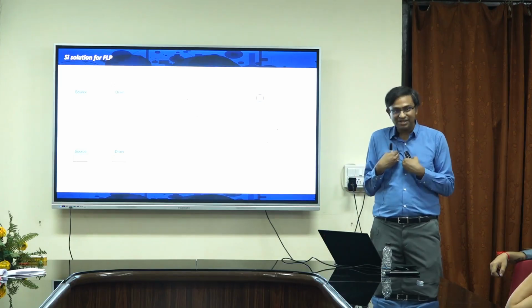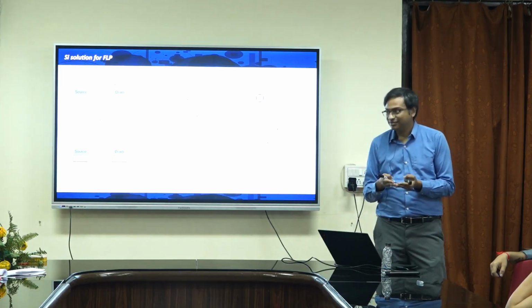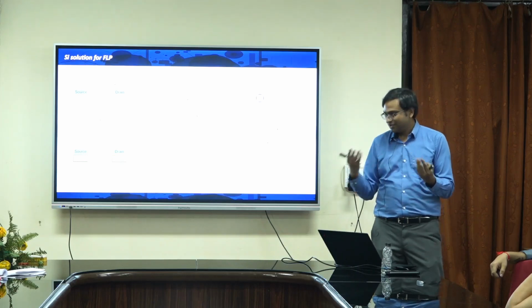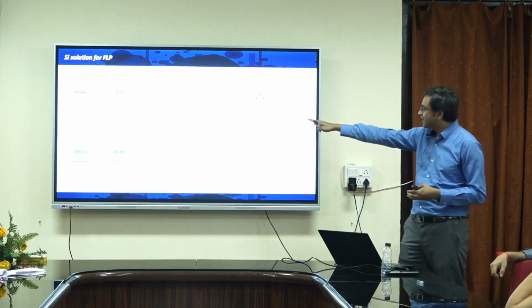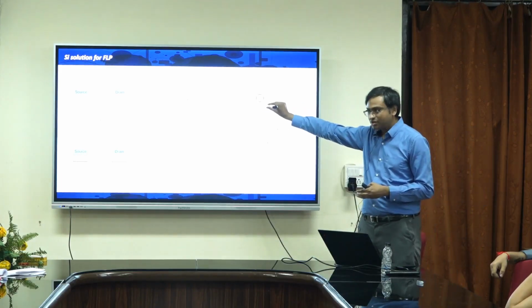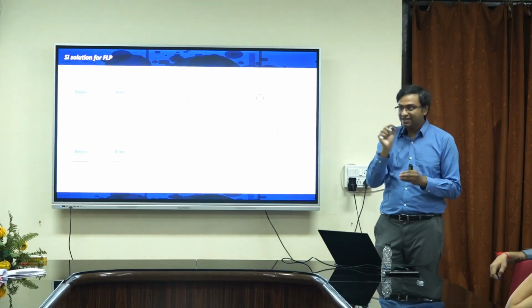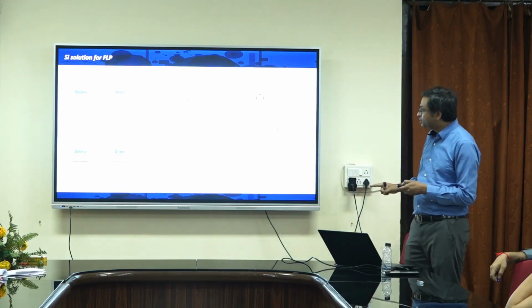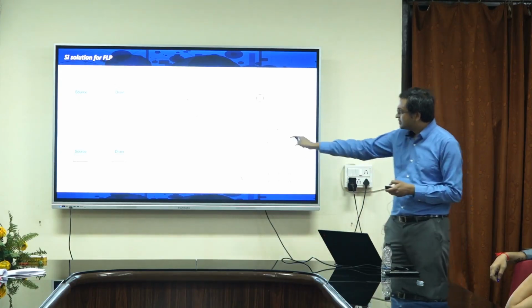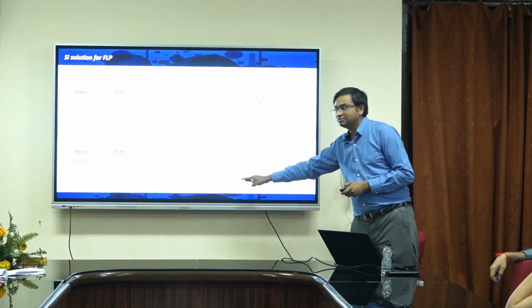We human beings cannot take advantage of a thinner wall, but the electrons can, because they are quantum mechanical particles. So if I cannot make it short, I have to make it very thin, and then I will be able to allow injection. And that I can do, because the width of the Schottky barrier depends upon the doping.